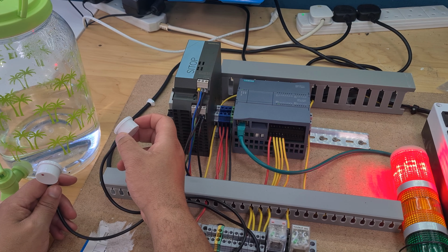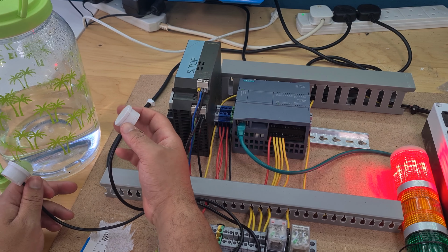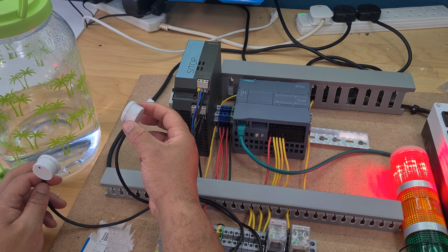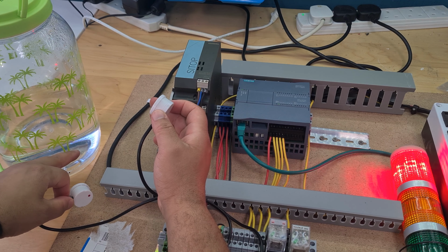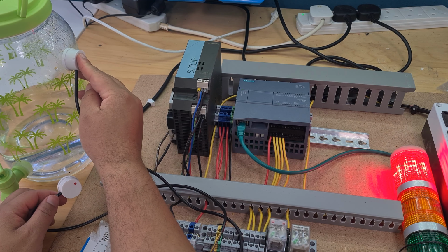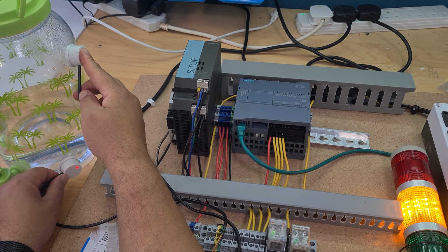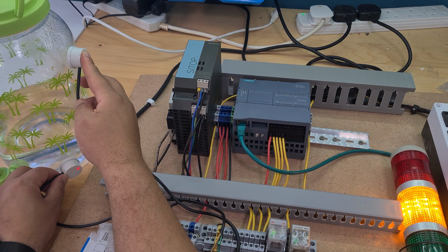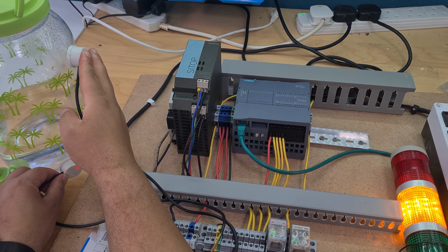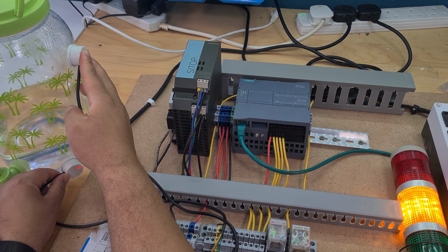The purpose of this program is that imagine I've got an oil tank or a water tank, and I've got two level sensors on the tank, one at the top and one at the bottom. So I have a high level sensor here and a low level sensor here, and I want to know both when my tank is full, at my high level, and also when my tank is empty, at my low level.